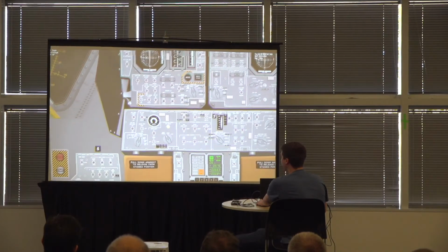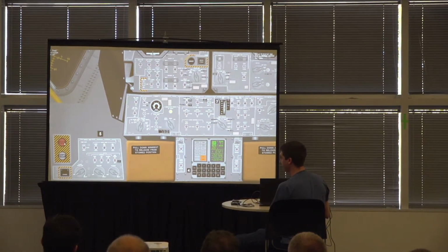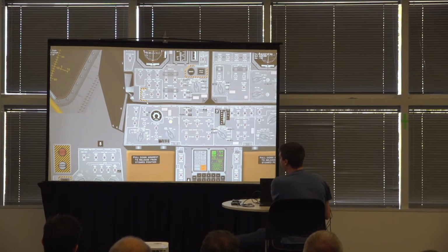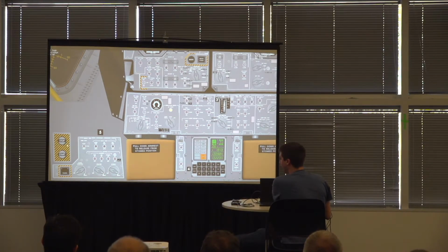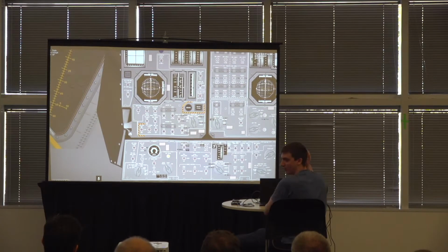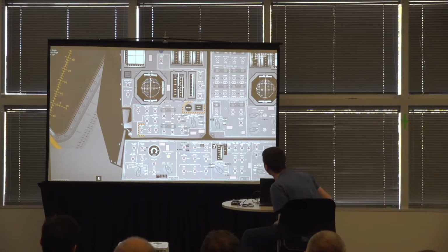If you look at my other buttons here, you'll see the engine stop button is still pressed in, and I don't have the ascent engine armed. The lunar module is wired in such a way that it doesn't care. If I press in this abort stage button, it will get me back to orbit no matter what. And it'll go all the way back to orbit with no other inputs from me. After that, the checklist steps say pull out the stop button, push in start button, and arm the ascent engine, but it's more of a formality to make sure everything keeps working. So yeah, that was the landing.